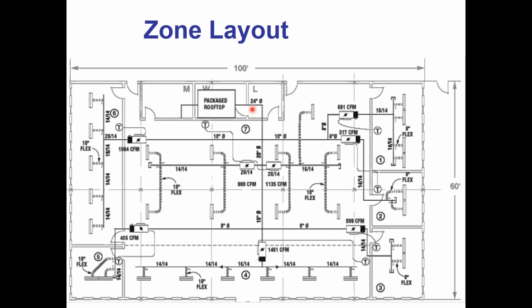So instead of putting the air handler into heating mode, each zone can have its own heater. Now we're showing duct heaters on here, but it could also be baseboard heaters. Baseboard is actually a little bit more comfortable. The whole idea of washing the window with the warm air, basically putting the heat at the point where the cold problem happens to be, which is the window. But I could have baseboard electric or baseboard hot water, or I could have ducted electric or ducted hot water. Any one of those would be acceptable depending on what I'm trying to do with the rest of my building and whether I already have a boiler for other reasons. This one happens to be duct heaters on here. And in this case, it happened to be electric, but it could have been hot water just as well.